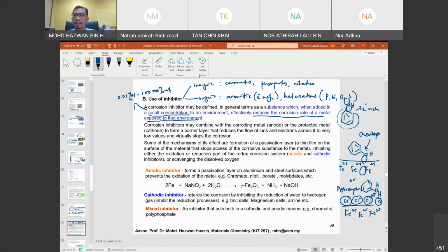In this case, if you form the interaction between the inhibitor species and the iron, what happens is that Fe2 plus cannot further oxidize or combine with hydroxyl ion to form rust. It becomes stable here. It forms a temporary product over here that makes it stable and unable for OH minus to react. Because there's no interaction between Fe2 plus and OH minus, rust cannot form. So that is actually the idea.